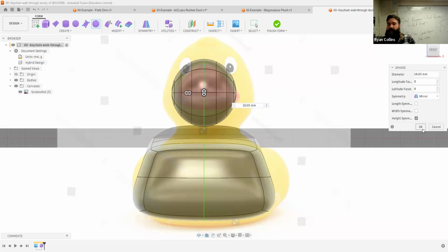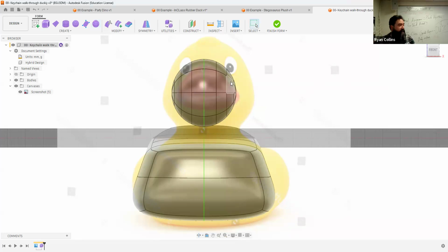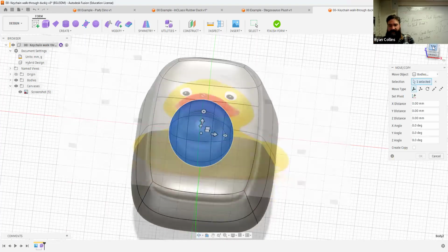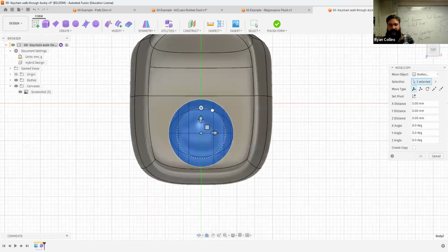Nice. If you accidentally selected the front plane and you're looking straight down at it, all I have to do is use the move tool, press M, the letter M on your keyboard, select the object, and the arc tool there. So if I accidentally did that and it's looking straight on, I'll look at it from above and just rotate.